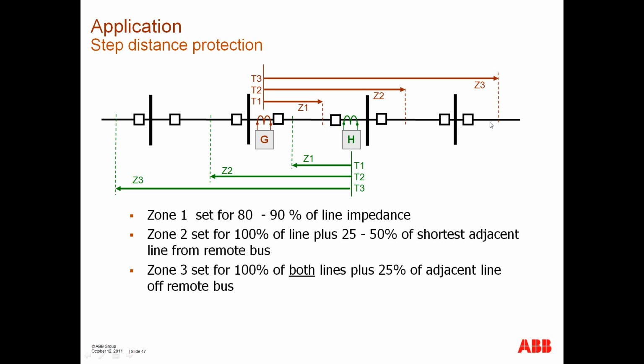Now, I will make some comments about zone 3. There's a lot of discussion as to whether they should be used or not, because they have gotten into a lot of trouble associated with the recent history of blackouts, where zone 3 has contributed to misoperations. So there is discussion going on in regard to the application of Zone 3.